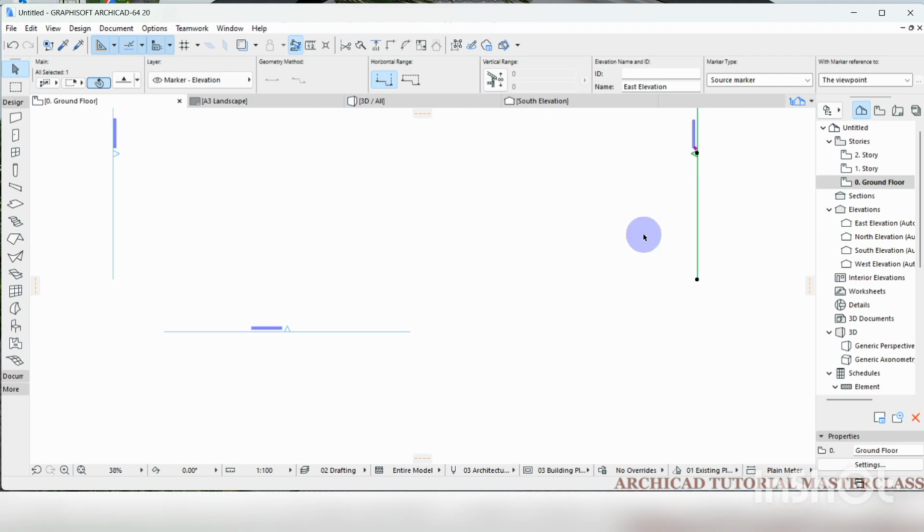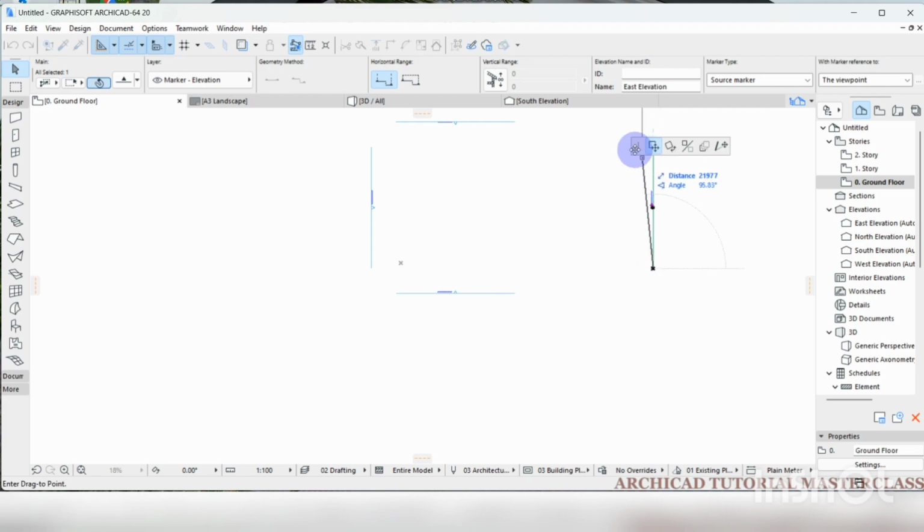Now as we have moved this one, we want to stretch this way. So you click on one side. When you click on one side, you see a different box has just appeared. In this command box, you can see stretch. So I'm going to look for stretch. If you still want to drag it again, it's still ready for dragging. But if you click on this stretch, you see that it can only stretch here. And when it is stretching here, you don't need to hold your shift again to stretch. So you can stretch it this way. You can also come here and click on it. You see, it's still under stretch because the last thing we executed here was stretch.